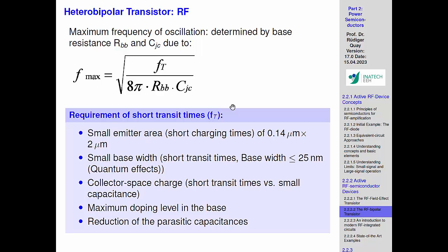So there you see the beauty of this. And if you do all this right, you can build a very nice transistor. So there's still a race whether the FET or the bipolar gives the best transistors on the planet. I'm more a FET guy, but the bipolars are actually at the moment in terms of power better. The best FETs we can make on this planet are faster. So FET is faster, bipolars are more powerful because they have more voltage. So that's the game.